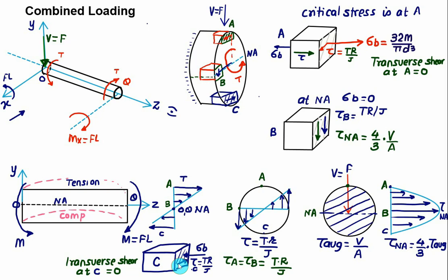So next our job is to understand the clear concept of the Mohr circle, how to find the principal stresses, the principal plane angle and the plane of maximum shear. So again, one more time we visit the Mohr circle and we'll do this in detail. This is the best way I can try to explain how to develop the state of stress. For this, the basic stress distributions must be known to you. Bending stress is a linear variation, shear stress due to torsion is a linear variation, and the shear stress due to shear force is a parabolic distribution.